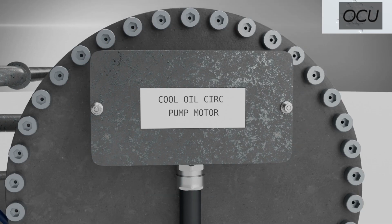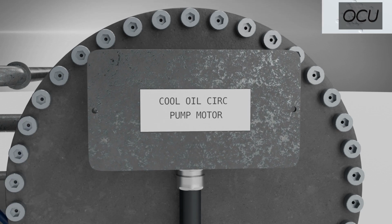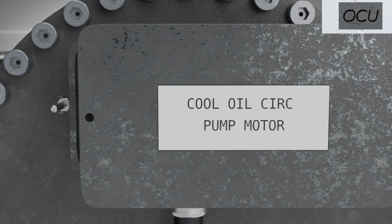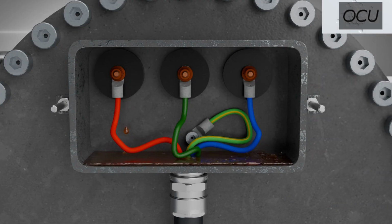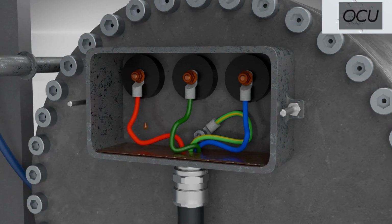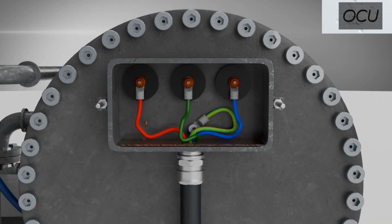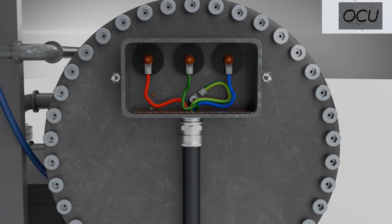Technicians were instructed to access the junction box cover and inspect for the presence of oil leakage in the OCU power junction box. At some point, a problem was discovered. Oil ingress was traced back to the motor junction box, which was found to be full of insulation oil. This indicated that oil had somehow migrated from the OCU to this location.